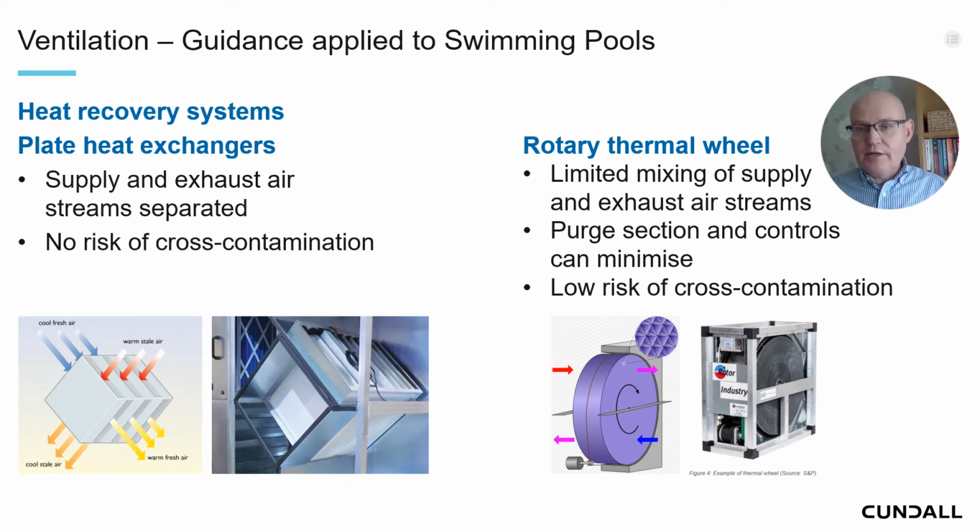A little bit of a risk in terms of return air. They're not designed to mix air, but there is a section where the wheel rotates where there may be a very minor carryover of air from the exhaust to the supply. Fairly low risk of cross-contamination, and probably the energy implications of switching these systems off and not running them far outweighs the risk of carryover from the return air.